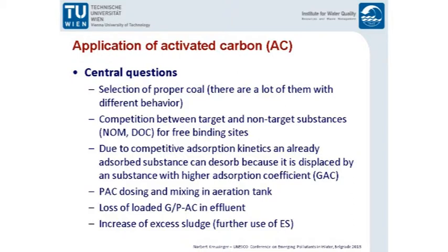We have the problem with competition. Most of the studies that you see about the applicability of activated carbon are with new, fresh carbon. But what happens when one substance adsorbs to the carbon, and then it's replaced due to the competition of adsorption by another substance, and then you lose it again in the effluent because the other substance has a lower concentration but a higher affinity to the carbon? So you really have a competitive adsorption process, and that at a certain point can lead to the situation that you lose again what is already adsorbed.